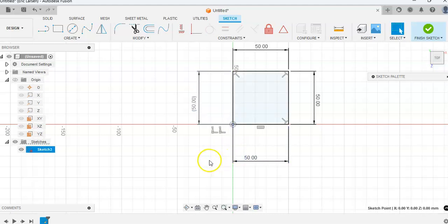Now we've dragged it down, and you also see that Fusion has created a coincident constraint. There are two coincident constraints here, and you can see that they were both put in for us. We didn't create them explicitly. I think the first coincident constraint says that the first line starts at the origin, and the second coincident constraint says that the final point of this line is also coincident with the origin, or the point at which we created the first line.